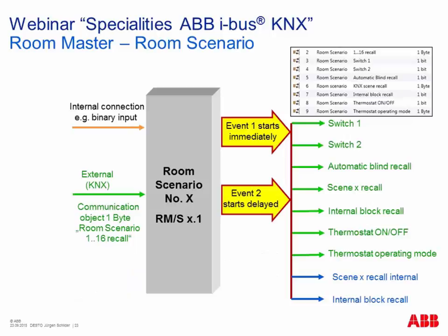And one special feature in the software of the Room Master is valid for all 4 Room Masters. We have the so-called room scenario intelligence inside. What does it mean? A room scenario is a special function which can be started either from any internal input of this device or externally via any telegram. And a lot of functions or telegrams can be sent out by using this room scenario to create a special room scenario in your project.